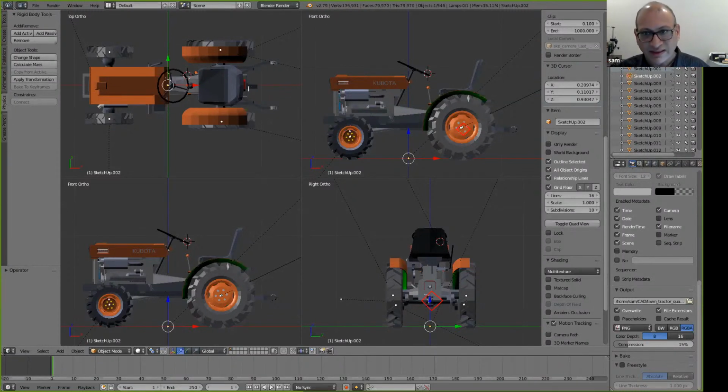Now, our robot in ROS always faces the front, and front is always X. In this case, your tractor is situated 180 degrees in the other direction. Your front of the tractor is. So first things first, your link will have the rotation element, which is 3.14, a 180 degree rotation on your Z axis, because you have to make sure that the front of the tractor lines up with the X axis.